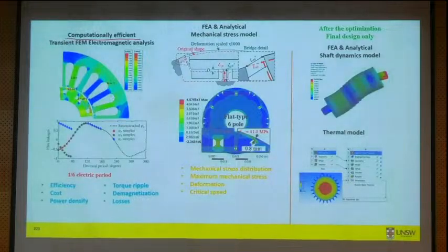What computationally efficient FEM does is, let's say for flux linkage, here it's showing the example of flux linkage, instead of trying to calculate each point of this flux linkage waveform, you simply do 1/6 of the waveform, because a sinusoidal waveform is kind of symmetrical, right? So if we know 1/6 of the waveform, the rest can be predicted.